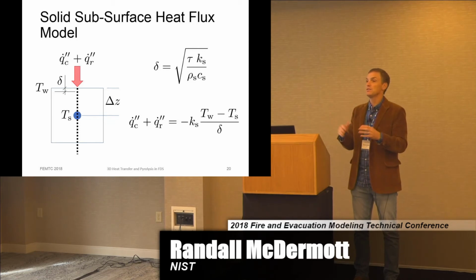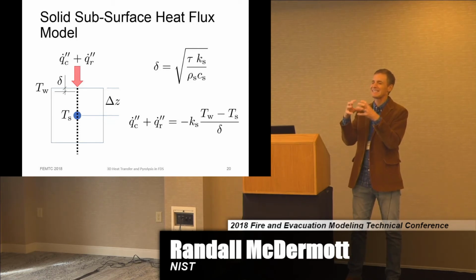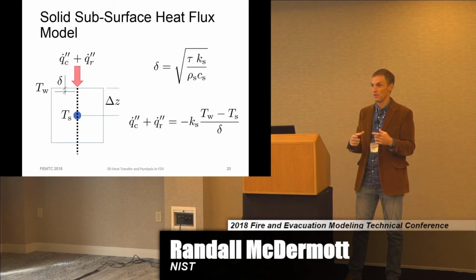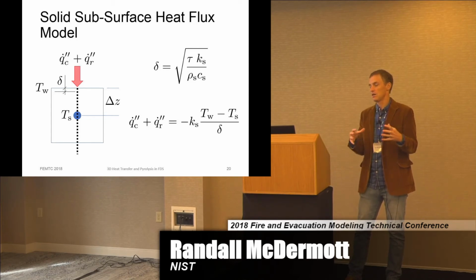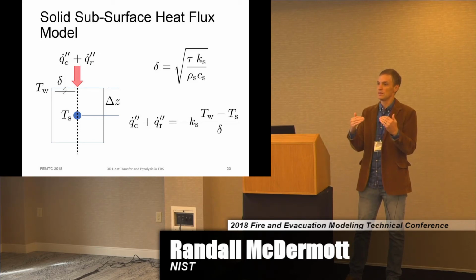Well, for pyrolysis, the obstruction actually accepts a surf ID in which the surf ID has a material ID, because all of the kinetics is still tied to the surf ID, and changing all of that machinery doesn't make sense. So there are two ways to specify material properties for an obst.